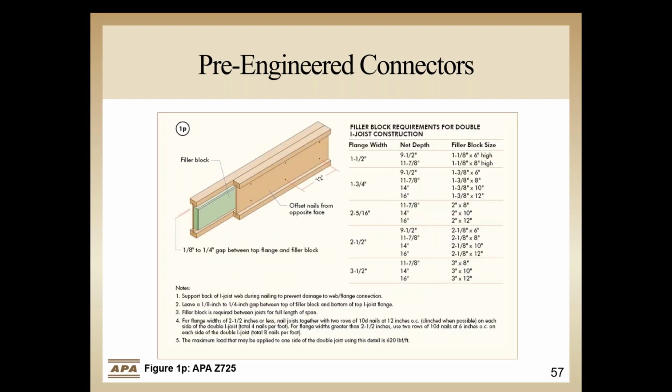These filler block requirements change with the joist series to correlate with the joist flange width to pack out the distance between the webs of the joist. Filler block details can be found in the joist manufacturer's literature.